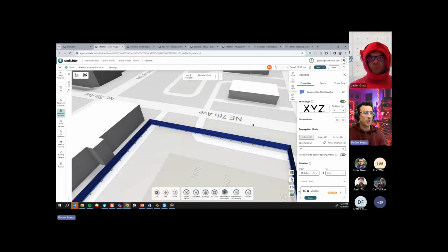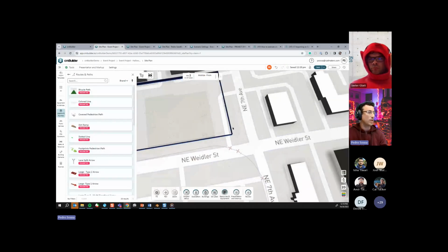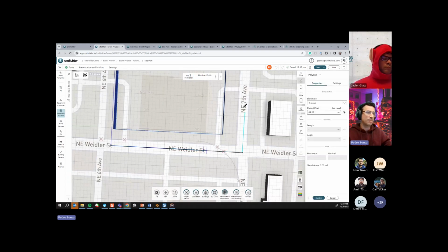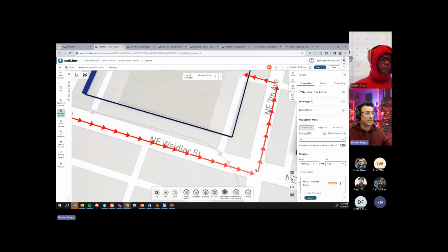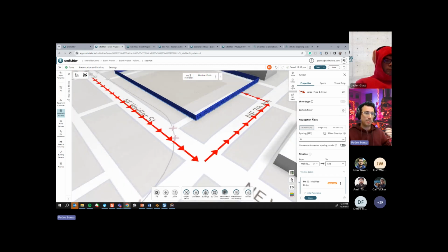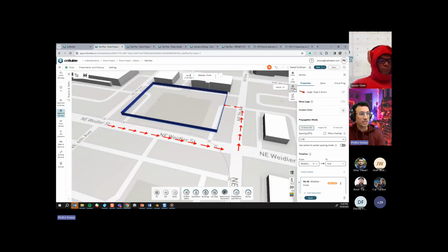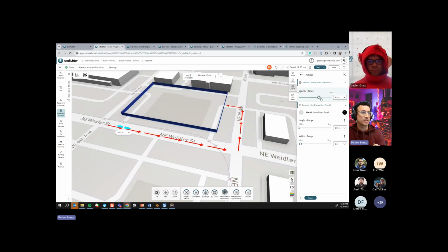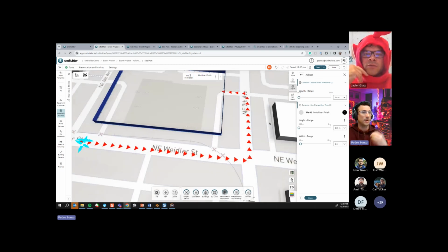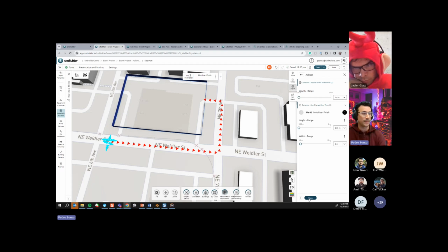Something that I've also noticed that a lot of people don't do, and it will be an interesting thing to touch base on, is that when you're putting arrows on your site, a lot of people don't notice that we have further adjustments to these patterns. Now these arrows are all touching each other over here. This propagation mode, we are going to change with UI in our upcoming updates. But basically, for arrows and things that you want to place on the ground like this, let's say cones or anything related to traffic controls, one of the good practices is to deactivate the allow overlap so you won't have arrows in the middle that have a different spacing, and also add a spacing for them over here. If you put in a spacing, you can have a cleaner look, and you can go even further by adjusting the shape of the arrows and making the length change. If you increase the length, you're going to have a pattern created with arrows that are super big. But if you want to create something cleaner like that, you can make a very small length and have more repetition of those triangles.